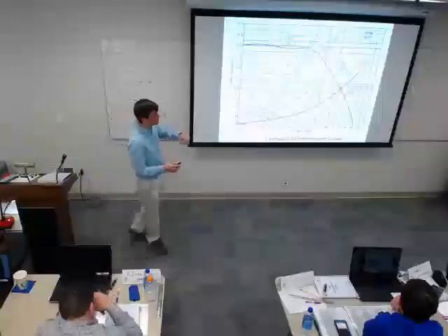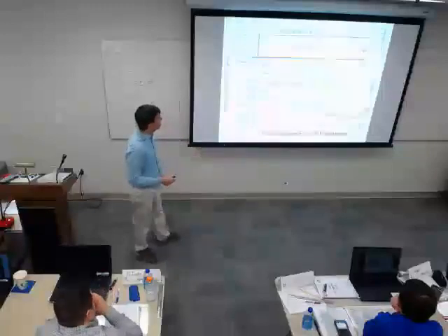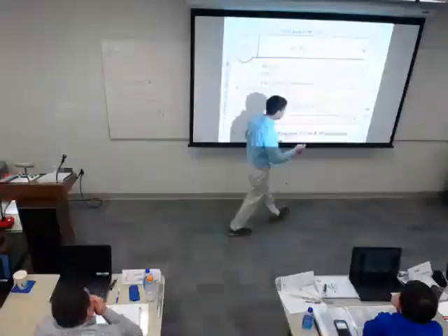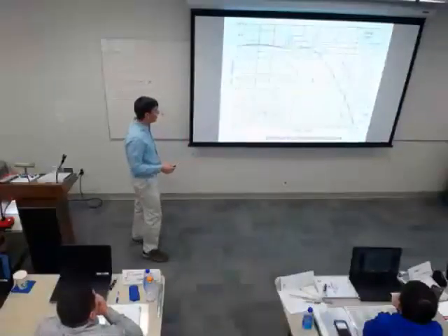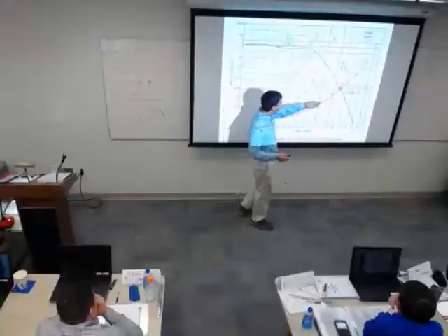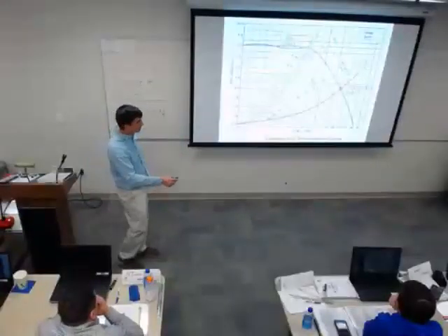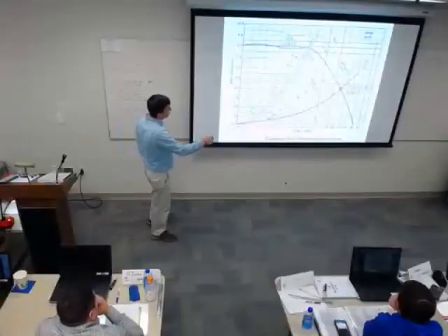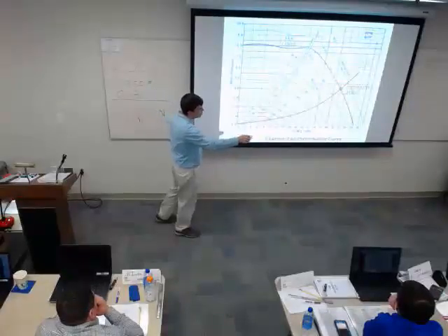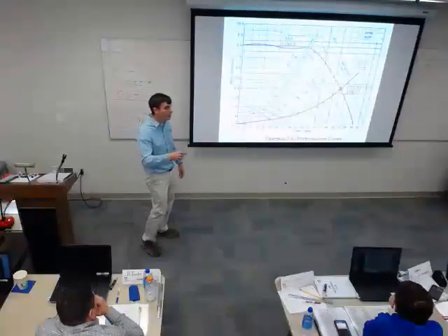If I go out and close the damper, so this was our system curve for the example we gave just a second ago, if I were to put a damper right here and close it, I would change my system curve. What would happen to my airflow? My airflow would go down because I created more resistance. I was operating at 4 inches of resistance. If I created another inch of resistance over that damper, I would then be moving 28,000 CFM. That's an important concept to understand.